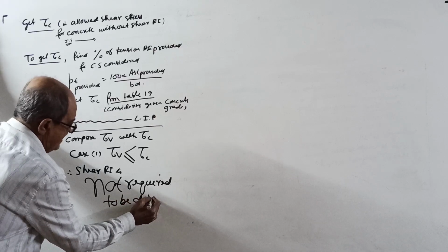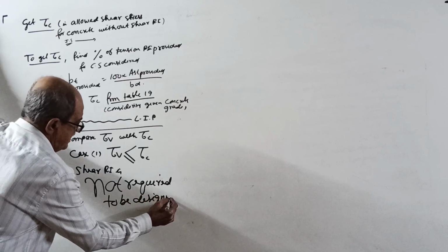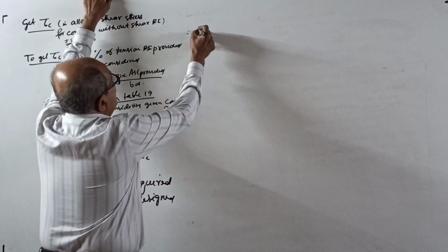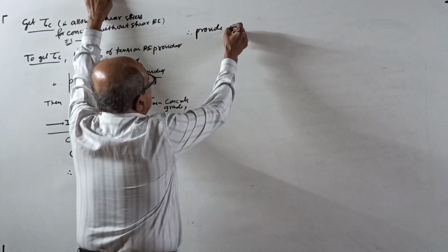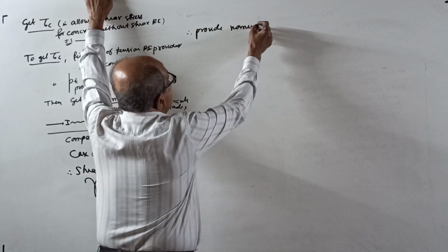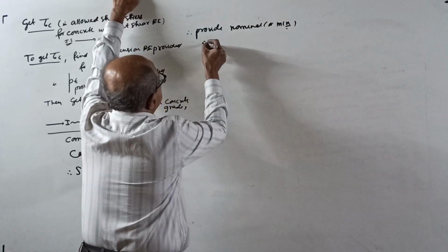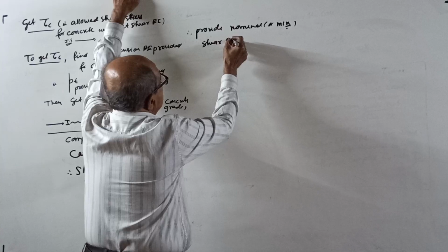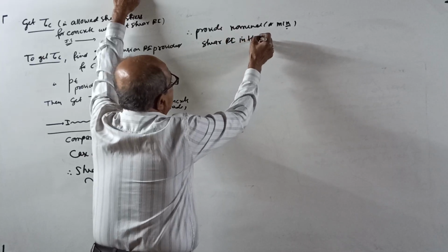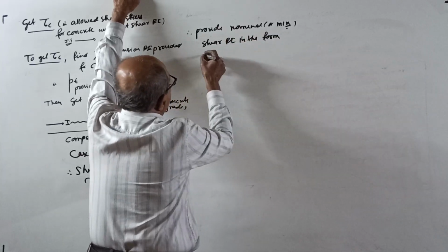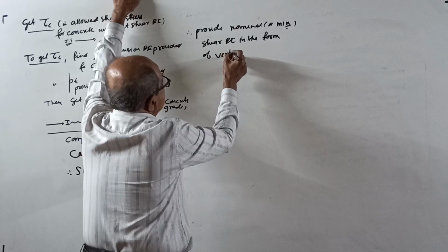No design, nothing. Not required to be designed. Therefore, provide nominal, or sometimes people say minimum, shear reinforcement in the form of vertical stirrups.